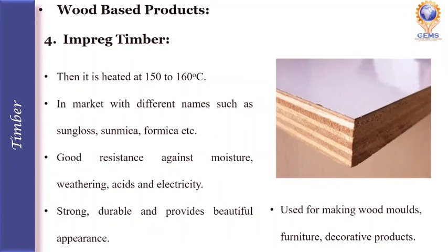This is available in the market with different names such as sunmica, formica and so on. The impreg timber has good resistance against moisture, weathering effects, acids, and electricity. It is strong, durable, and provides a beautiful appearance also. It is used for making wood molds, furniture, and decorative products.